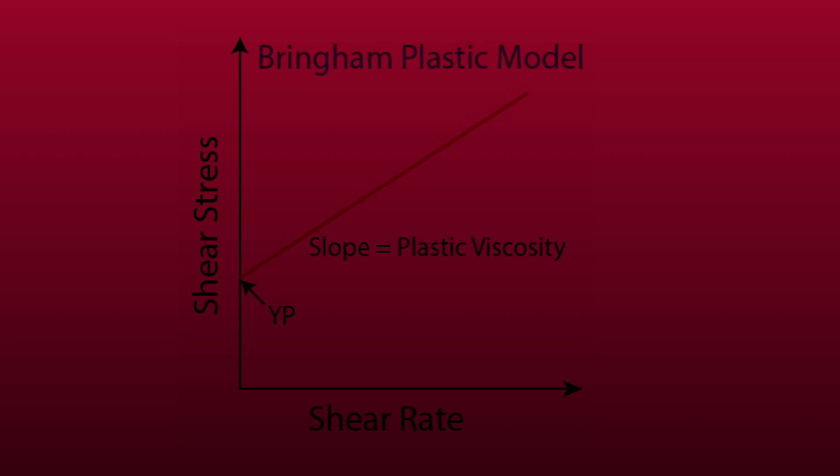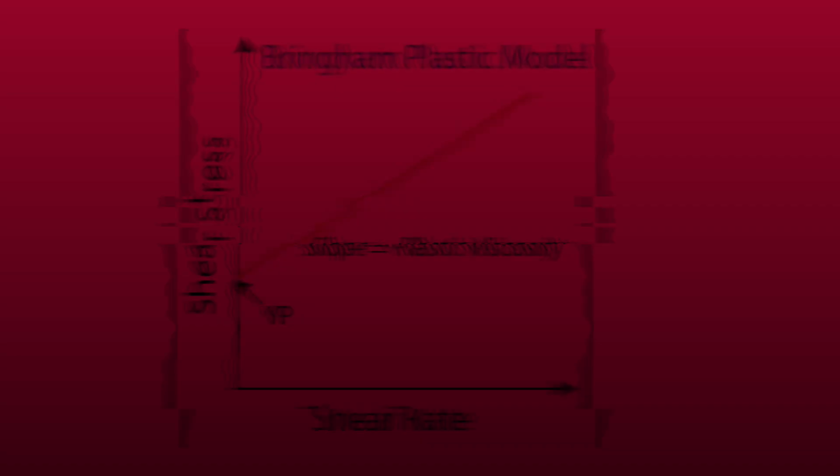One of the most common rheological descriptions used in drilling hydraulics is the Bingham plastic model. This model assumes the fluid behaves like a rigid body until a certain yield stress is exceeded. Once that threshold is reached, the fluid flows with a linear relationship between shear stress and shear rate. This is particularly useful for drilling muds, which must be able to suspend cuttings when circulation stops. The presence of yield stress prevents solids from settling under static conditions.